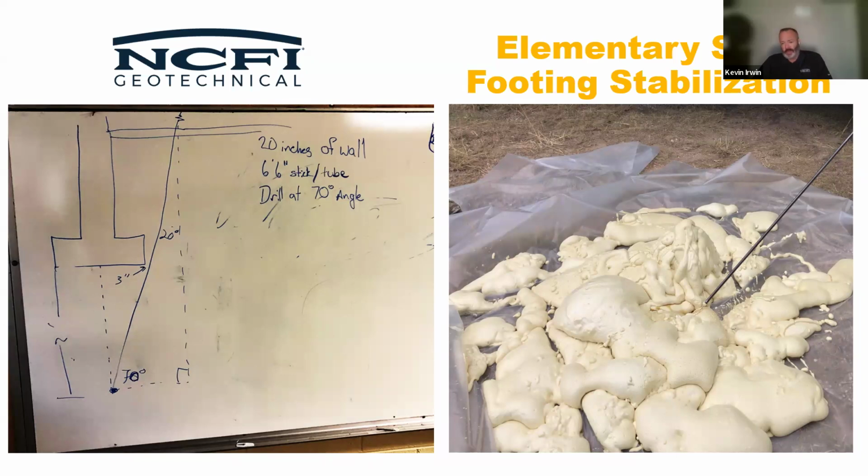Now, the picture on the right, I'm not going to try and do a video here, but it looks like it's just a mound of foam. What you're seeing is the actual length of tubing that we were using, and we were turning the heats up to get our chemical to react as quickly as we could as it was coming out of the tube. We didn't want it to spread further. We wanted to minimize how far the chemical spread underground side to side, and we wanted it to bunch up and get that confinement quickly, rather than lensing and soaking further out. I wanted it to get a lot more quick expansion to stabilize that right there.